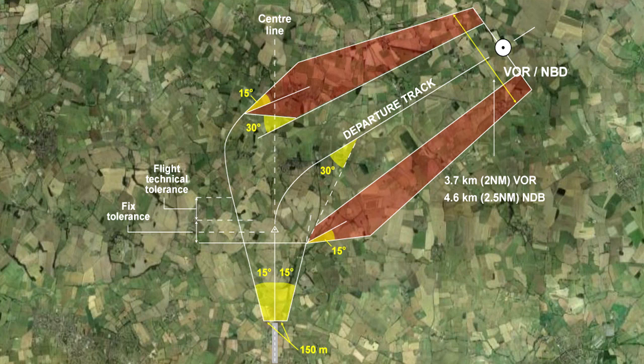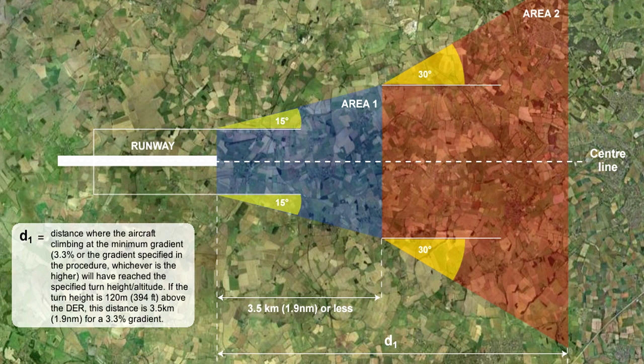In the event of in-flight emergencies, post V1, aircraft operators are required to provide contingencies that deal with safe operation of the aircraft during this phase of flight. An omnidirectional departure procedure is designed when no track guidance for departure is available. Departure criteria are developed using undefined omnidirectional initial departure tracks. In practical terms, this means that once off the end of the runway and at a safe height, aircraft may be navigated in any direction required to achieve the initial en route point.